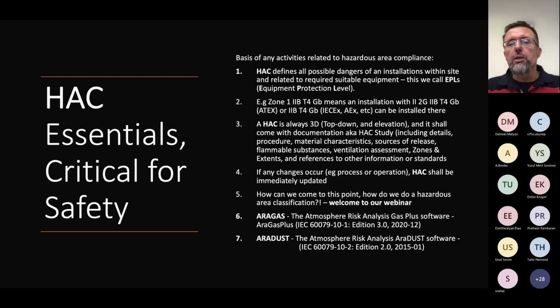The basis is the IEC standards, the NFPA standards, the NEC standards, because that's very important. Our imagination was to create a software which can be used internationally, which can give you the solution internationally. And let us not forget, what is the outcome, the output of a hazard classification? Always the EPL, always the EPL.